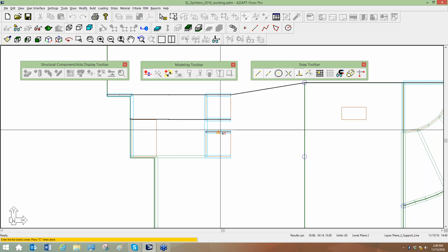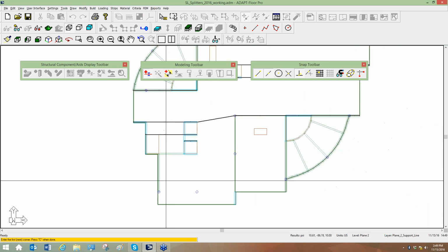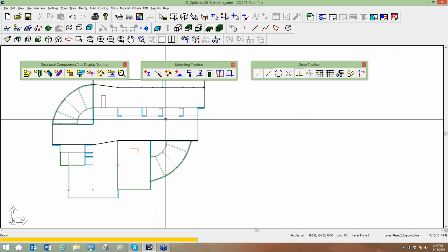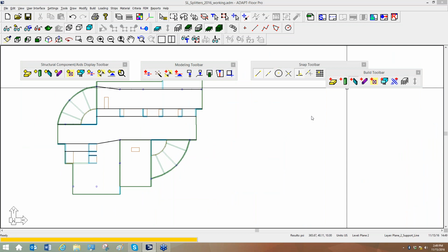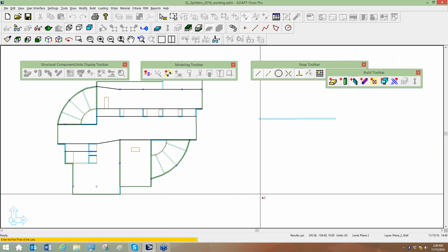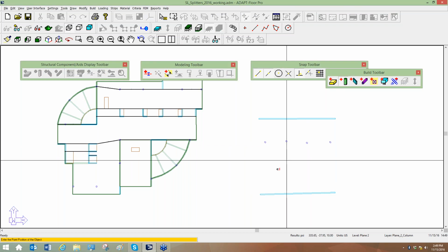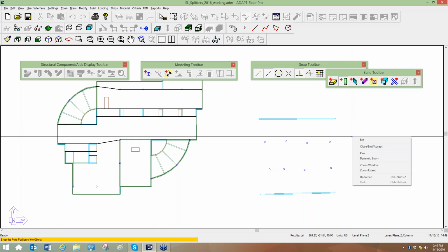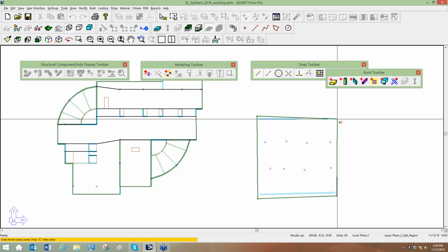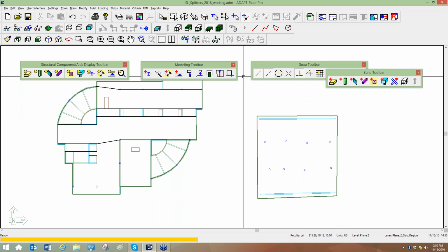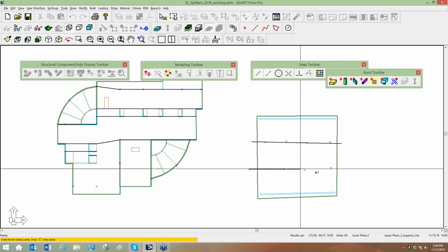I try to add support lines over any wall in the direction I'm working on. If you have a situation where, let me just draw a quick example. Let's say we have a wall here, and we have a wall down here, and then I have a column, column, column, column, and my slab is something like this. So sometimes we'll see slabs which have a support line here and a support line right there.